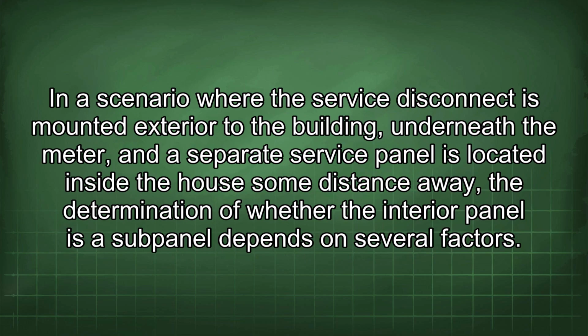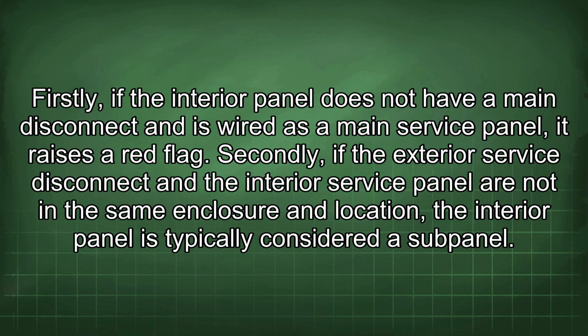In a scenario where the service disconnect is mounted exterior to the building, underneath the meter, and a separate service panel is located inside the house some distance away, the determination of whether the interior panel is a subpanel depends on several factors. Firstly, if the interior panel does not have a main disconnect and is wired as a main service panel, it raises a red flag. Secondly, if the exterior service disconnect and the interior service panel are not in the same enclosure and location, the interior panel is typically considered a subpanel.